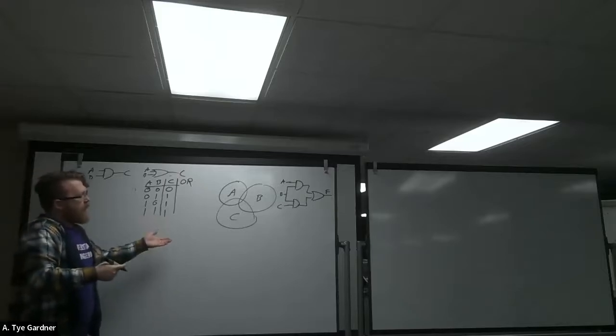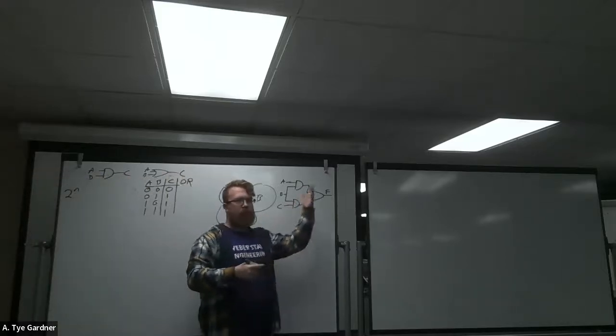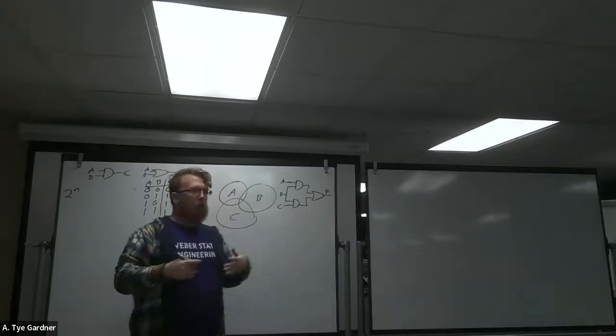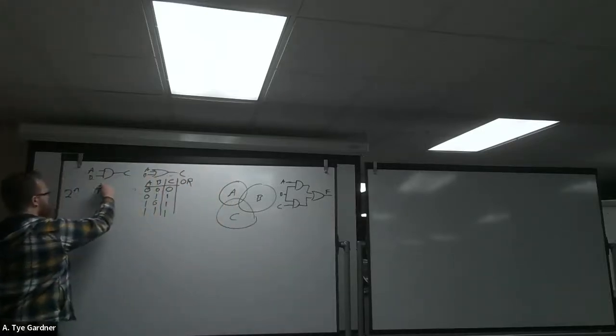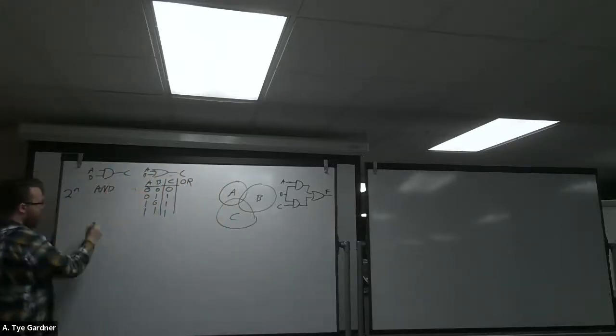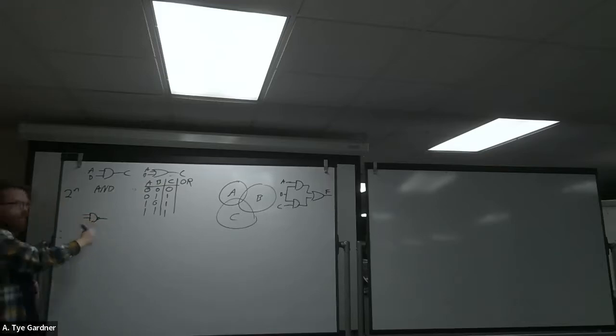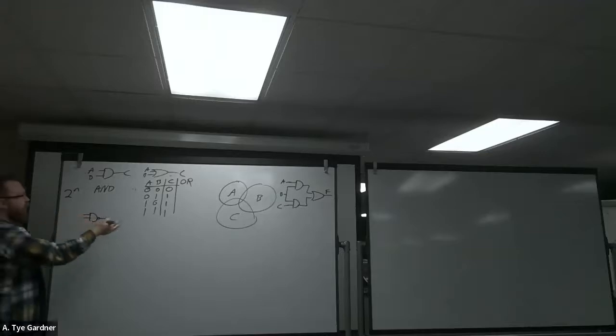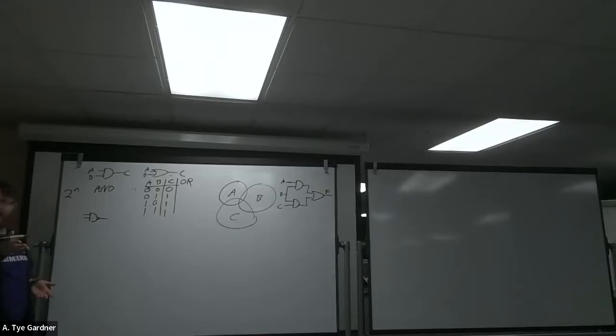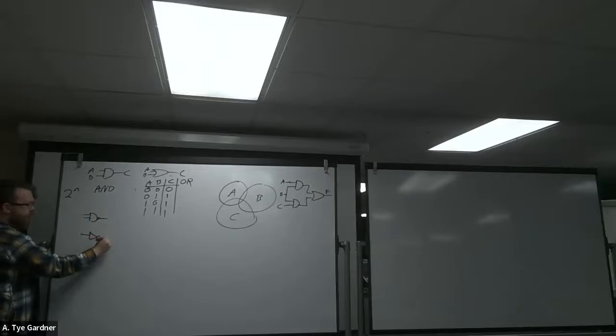So what we say is, well, I can write a Boolean expression for this. We've kind of talked about this, where I have the words AND, OR, NAND, which is not AND, right? If I drew the truth table of the AND gate, the NAND is just anywhere there was a 1 becomes a 0, anywhere there was a 0 becomes a 1, right? Because this bubble is an inverter. Inverting means just turn 1 to a 0 or 0 to a 1. It's truth table.